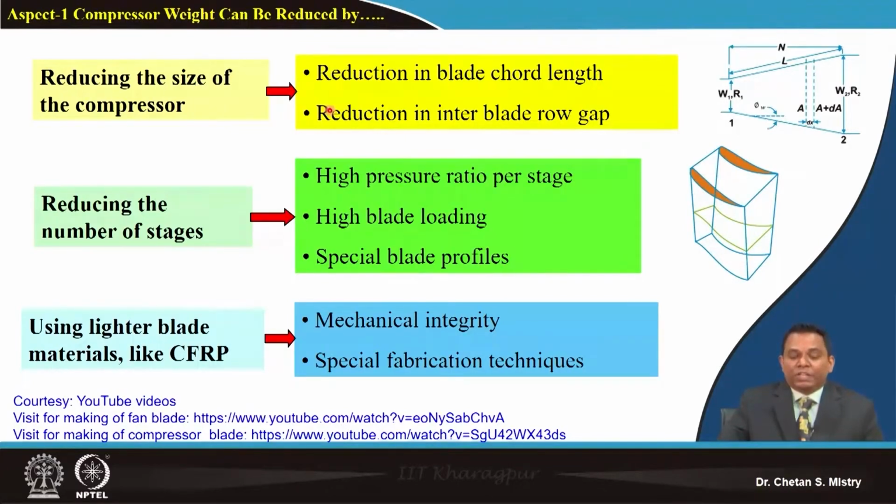Okay. Next is the reduction in the gap between rotor and stator, or maybe the gap between two spools. As we have discussed, the gap between rotor and stator is defined as a percentage of chord. Suppose we arrange our rotor blade and stator blade nearby, that will change the performance, or lead to higher noise.